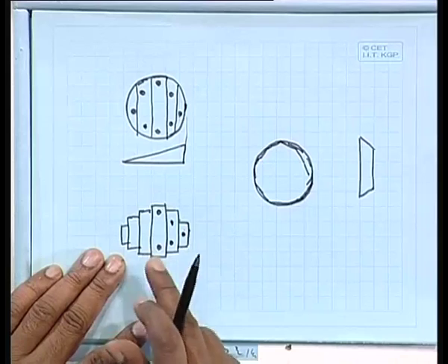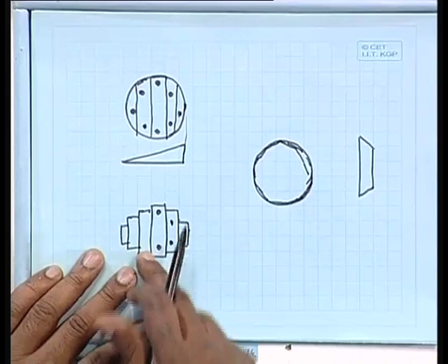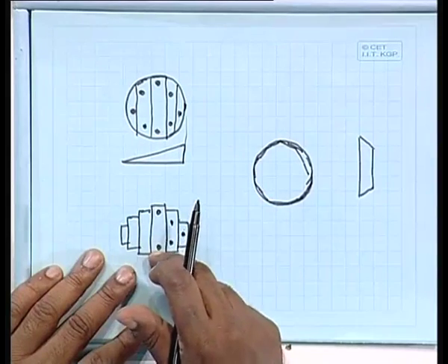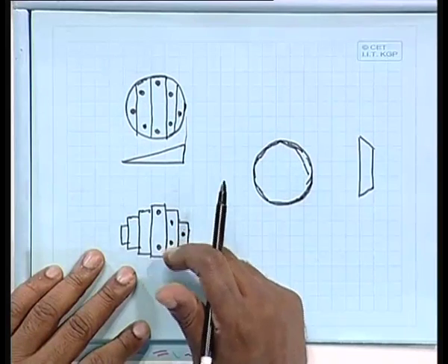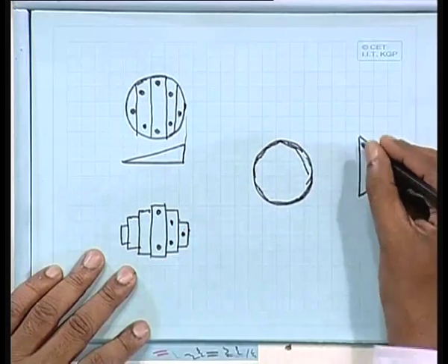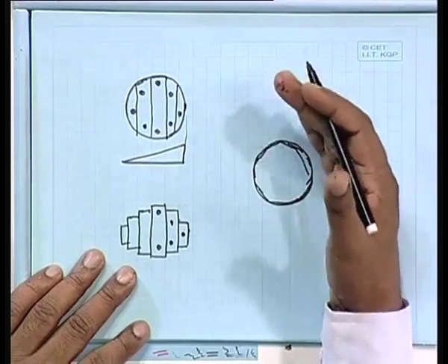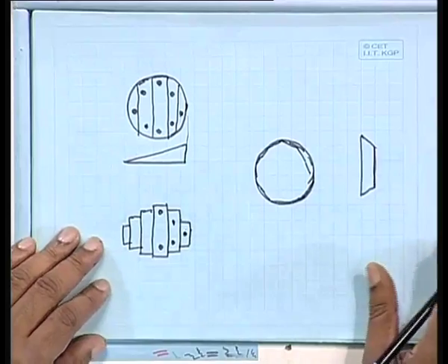That means in this case, if you can develop it for rectangular one, you can do it for the circular one also, by doing that equivalent section in this fashion. That means modeling the circular section in this fashion. Whereas, if you would like to be a little bit more adventurous, then you can take your trapezoidal one, which will be closer to your circular section. So this way you can make your own design.